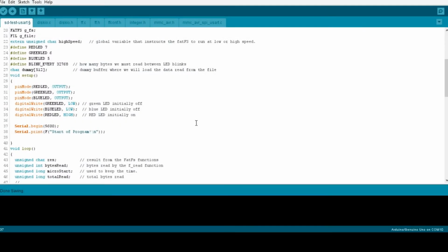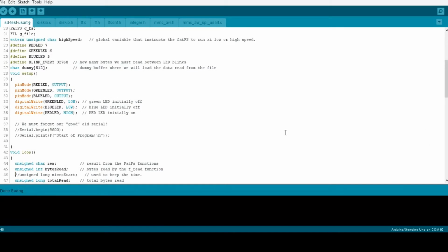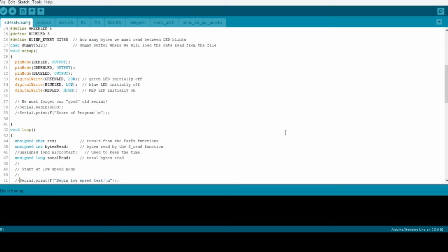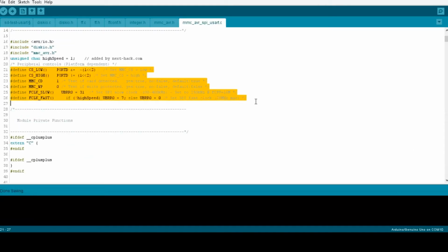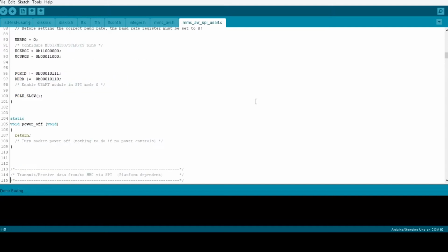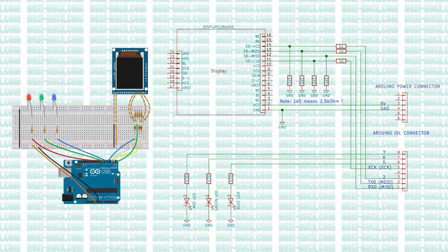Let's implement the USART test code. Unluckily, since we are using the USART to communicate with the SD card, we cannot send any data using the serial port for debug. We also disable the interrupts, as we have no way to print out the elapsed time. We will use the scope. We modified the FATFS to use the USART instead of the SPI. We also modified the schematics for the USART implementation.